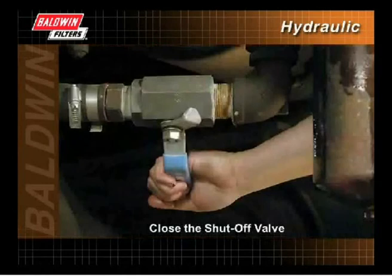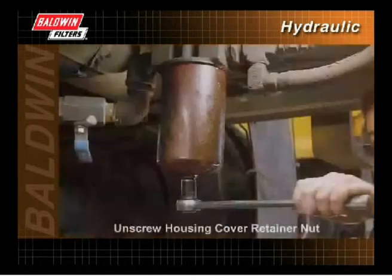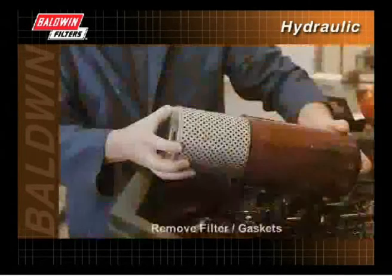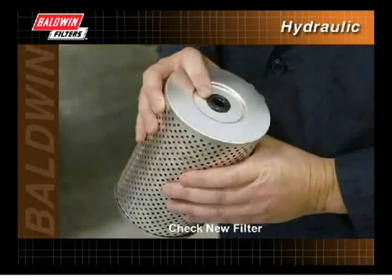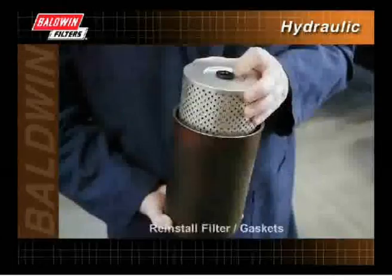When servicing, first close the shutoff valve to prevent spillage. Clean the outside of the housing before removing the filter to keep contaminants out of the hydraulic system. Unscrew the housing cover retainer nut from the filter head to open the housing. Remove the filter and all old gaskets. Wipe the inside of the filter housing with a clean cloth to remove contaminants. Check the new filter to make sure that all required gaskets and seals are included. Also, inspect the filter for damage. Damaged filters should not be used.